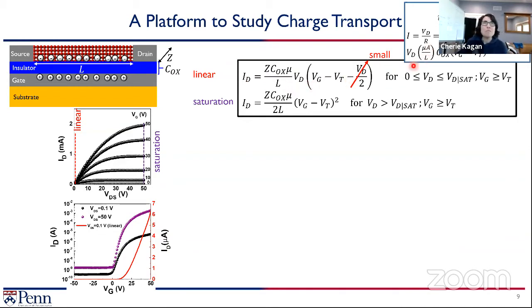Minus this one-dimensional term, because we're really thinking about a thin two-dimensional layer, where the carrier moves within a sheet and not through a volume in the transistor. So if I think about the characteristics in the linear regime, it really is operating like a variable resistor. As I tune the gate bias, I'm tuning the resistance and therefore the current.